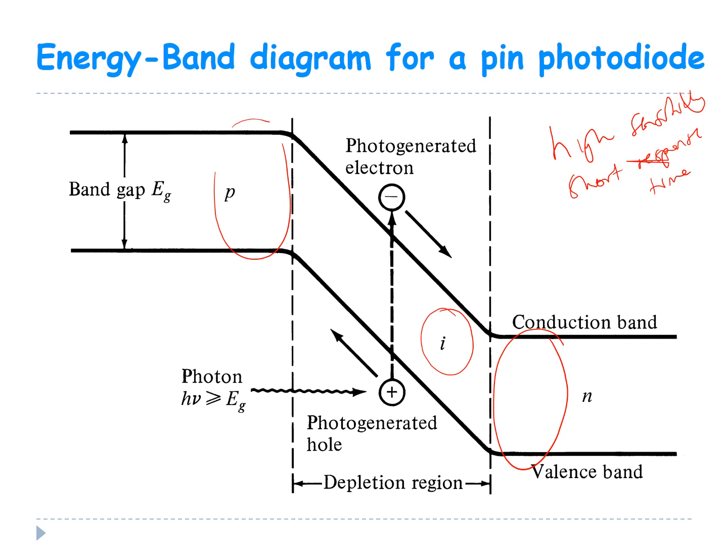One way to achieve that is to make a PIN photodiode. Let's say you start by depositing a P, and then you deposit an I, and you deposit an N. You should take special care in determining the thickness of the N region. The thickness of these devices is very important. You can determine it through device simulation, or experimentally. You have devices with varying thicknesses, you check their performance, and then you can extrapolate and come up with the required